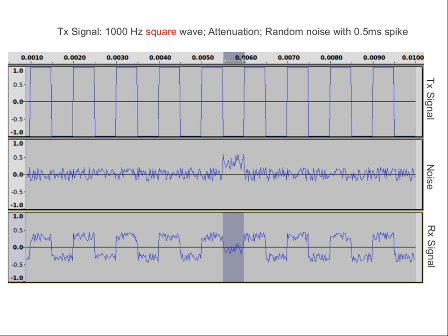At the start of the lecture we said the more components, the more accurate our signal is. We had an example over here. Signals A and B had 2 components. Signal C had 3 components. The advantage of signal C was it was more accurate. It's the same here. Why? See what happens. The signal is a square wave, an infinite number of components, and in fact an infinite bandwidth. Same noise. If we look closely here, we see on average the signal is low, negative, which matches what was transmitted.